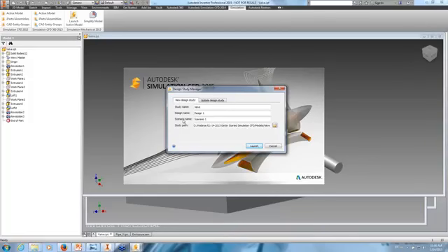What if I change the temperature? What if I change the flow? Keeping the same geometry but different boundary conditions, or materials for that matter. So basically you have 3 levels here. The biggest level is the study. Under that you have designs, and under that you have scenarios. You can keep those as default, or you can give them different names. That is up to you. I'm going to stay with the default names and click on Launch.